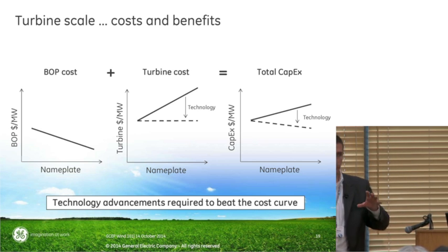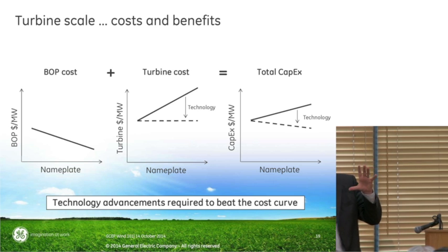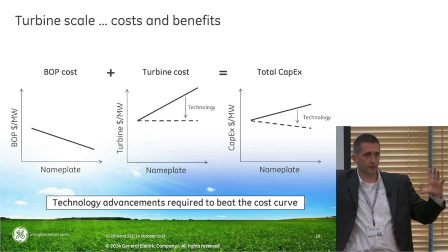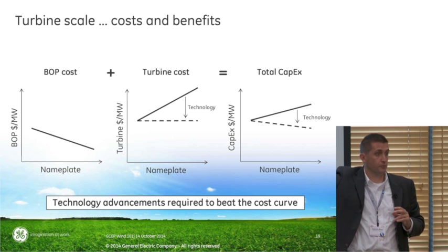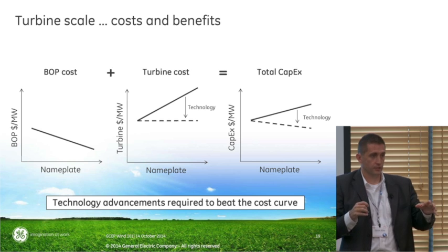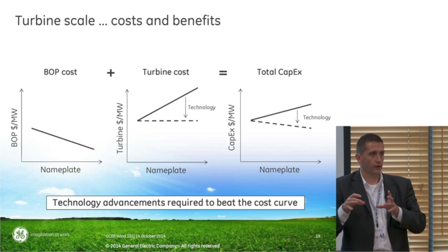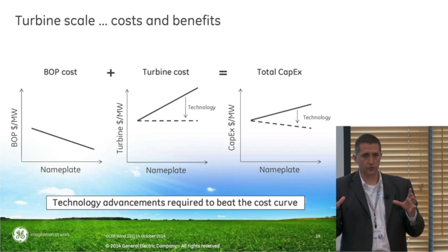Yeah, so an important point when you scale these things up and you get bigger and bigger rotor diameters is how fast that tip is moving. Typically the limitation, you do get into places where you need to look at the aerodynamic performance at the tip. And there is work going on in terms of how you model that and make sure you get the right structures on that. But it also is very often limited by the noise created. So there are always noise constraints associated with that.